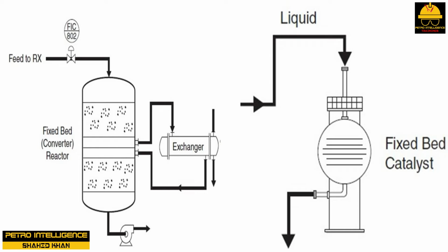bottom of the bed. Several design considerations must be taken into account in constructing a converter. The free area of the packing must be great enough to allow an acceptable pressure drop through the reactor at the design feed rates. The packing must be strong enough to resist collapsing at design conditions over a reasonable length of time. If the packing is a catalyst, its active life should be long enough to produce production runs of economic duration. The design of the beds should provide for removal of the heat of reaction so that there are no hot spots in the bed.